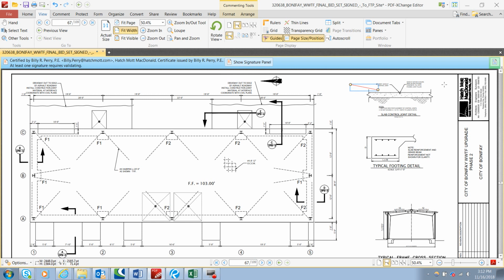So we put in break lines. This just means continued beyond this area, and there's two sets of break lines here. This line with this squiggly middle, that's just continue beyond. So you will use these a lot as you limit your work. The break line could also be almost a flat S, as this one is. So the same situation. It's just saying work beyond.